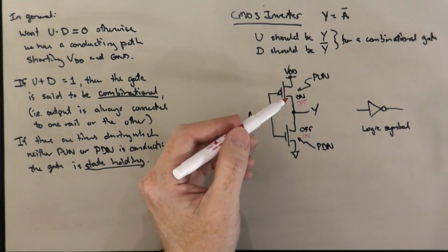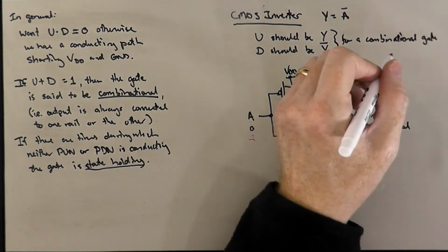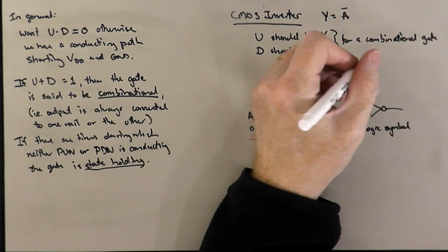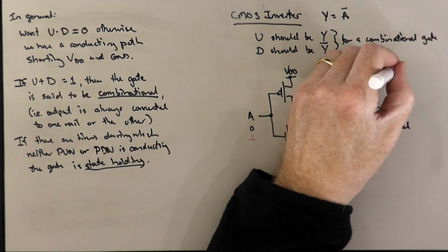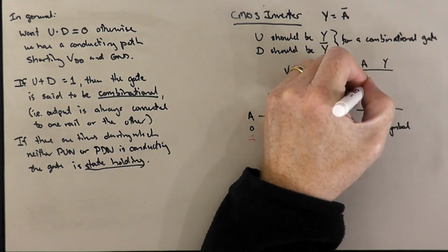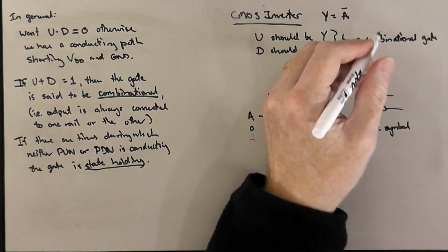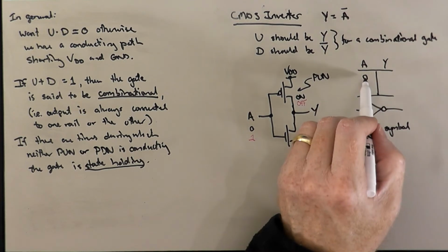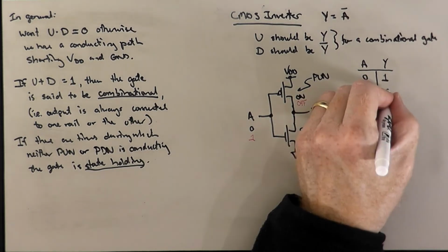Okay, so that's a CMOS inverter. We'll talk a little bit more about the voltage transfer characteristic of the CMOS inverter as sort of a prototype for logic gates. We sometimes will also talk about something called a truth table, and so the truth table for this circuit would be something represented like this. So we have a table that gives the possible values of the inputs. In this case, there's just 0 and 1, and then the value Y. So Y, when A is 0, not 0 is 1, and not 1 is 0. So this would be the truth table.